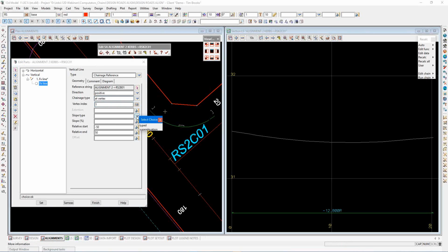Specify the value of my start slope. Now you can either select type and enter it manually. If you are using speed tables, you can use the super elevation option. We're going to use typed. My standard crossfall on my roads is -3%. And then my construction lengths, well, I want to construct this starting grade just before the start of my horizontal geometry.